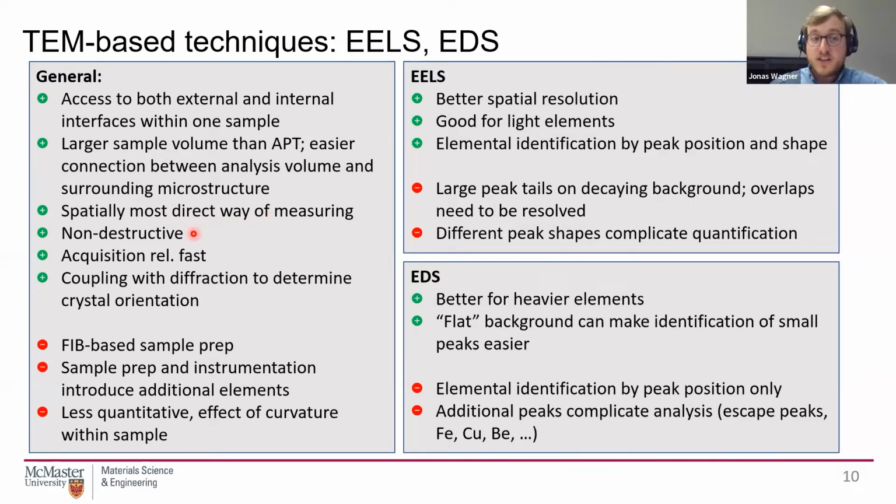It is also non-destructive. That means you can make a sample once, you can come back, look at it several times. Once you have the sample, the acquisition is relatively fast. And one last big advantage is that inside the TEM, you also have access to different diffraction techniques like selected area diffraction that helps you to further characterize the interface, for example, in terms of misorientation and grain orientation.